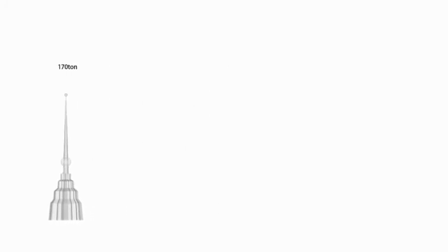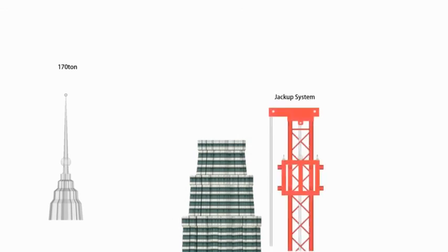Since the pinnacle was to have a final weight of 170 tons after installation, it deployed 8 jacks and 4 lifts, each withstanding 25 tons, creating a jack-up system capable of lifting up to 200 tons. In addition, the guide rail method was used to reduce the impact of wind load during lifting operation and to reduce the need to correct the pinnacle after completion of the work.